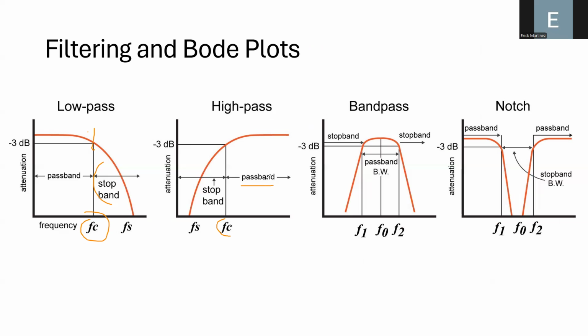Okay. Also notice that it is impossible to have ideal filters, because you can see here that there is a certain decay over time. Sometimes we want to have this abrupt change, in which we are attenuating the information very precisely. But in reality, we cannot do that, because filters are not ideal. They have a certain decay when we analyze them in frequency.